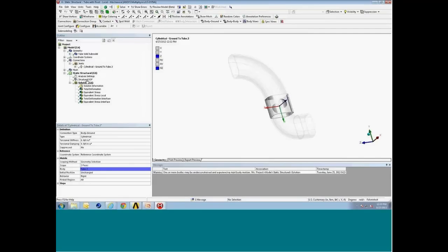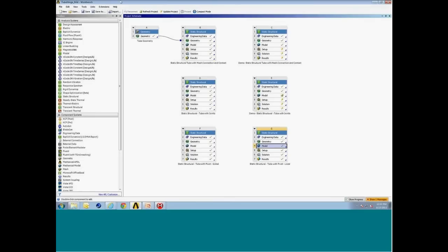So what I'd like to demonstrate is the use of a submodeling ACT extension, Ansys Customization Toolkit extension. These are extensions you can install. If I bring up our Workbench main menu, we have an extensions menu, version 14.5, that lets you install compiled extensions, whether we get them from the Ansys customer portal or we create our own.